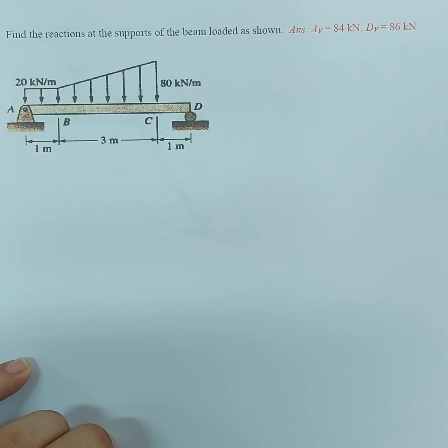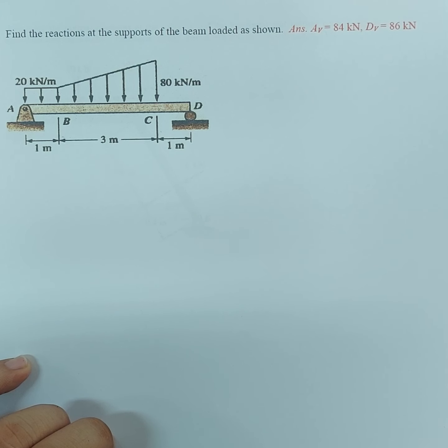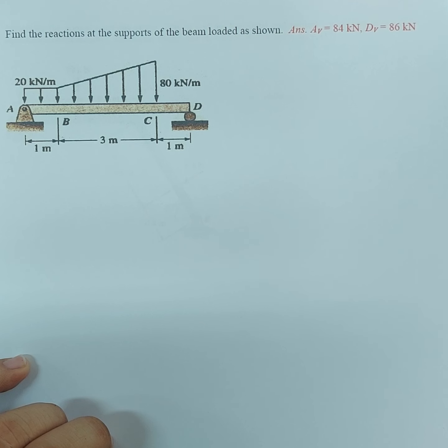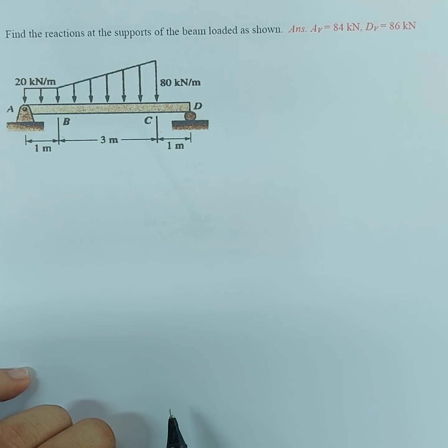Take note na yung equation natin tatlong equations lang. So summation of forces along x is equal to 0, summation of forces along y is also equal to 0, and summation of moments should be equal to 0. So yun ang i-apply natin. Okay? So dapat yung number of unknowns natin, therefore, dapat ay tatlo lang din. Since you only have three equations of conditions of equilibrium, no? For 2 dimensions, of course.